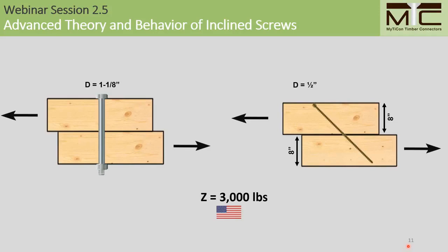Bolts, of course, will always be a part of timber engineering, but compared to inclined screws, when we use bolts, we will also have to consider things like pre-drilling, controlling fabrication tolerances, increased assembly time, and further reductions in the cross-sectional area of the timber. So this makes bolts less feasible for high-capacity connections, especially in mass timber design, where through penetration is not always viable.